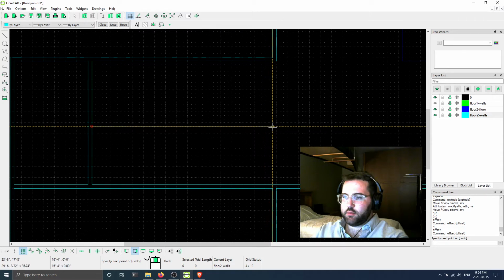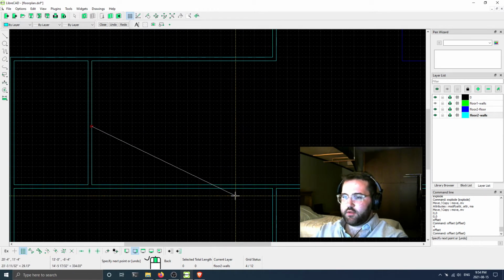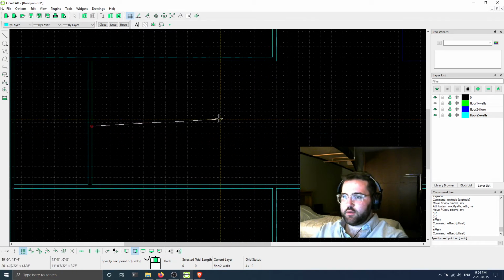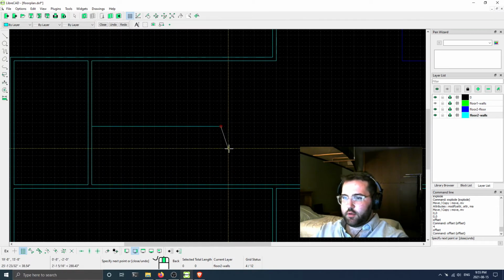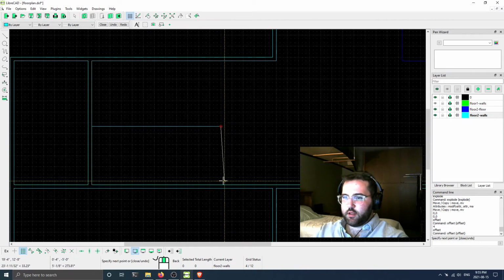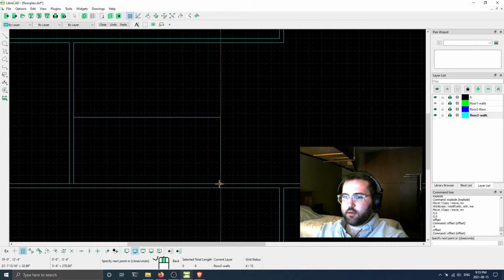And probably gonna want to place the door to the master bedroom right here, so we can make a hallway that's faced out here from the closet. So how far over would this be? This would be 10 foot 8, 11 feet, 12 feet. I'm gonna go with 11 foot 8. And then just drag this down. Still have a good grid snap point, so we just snap onto the face there.